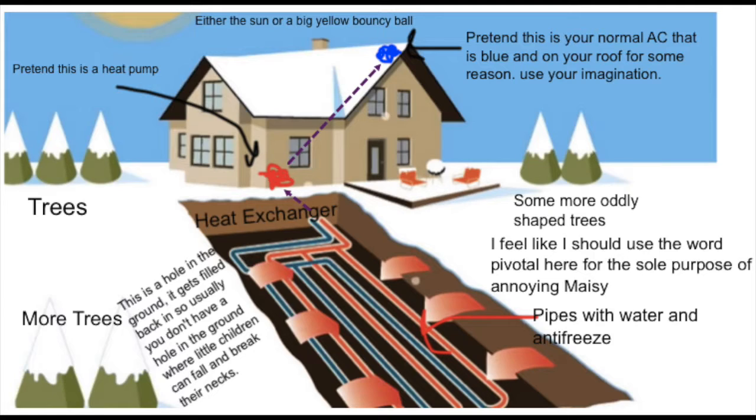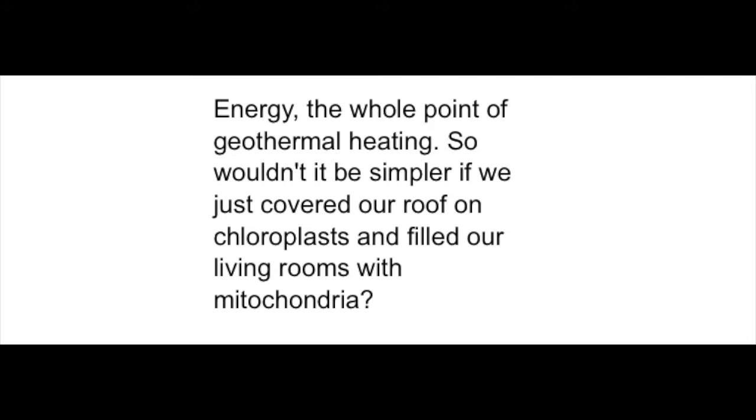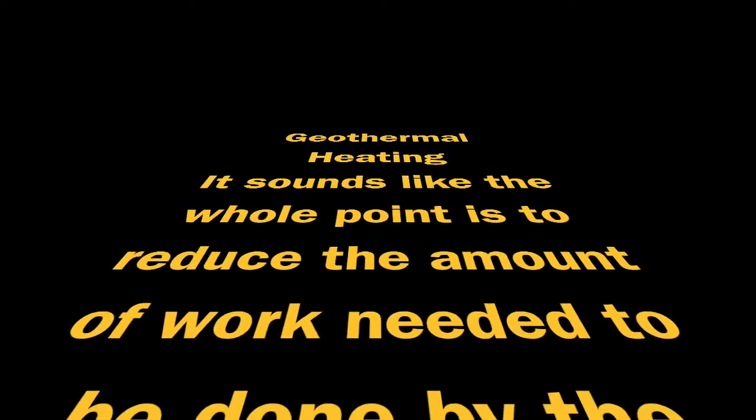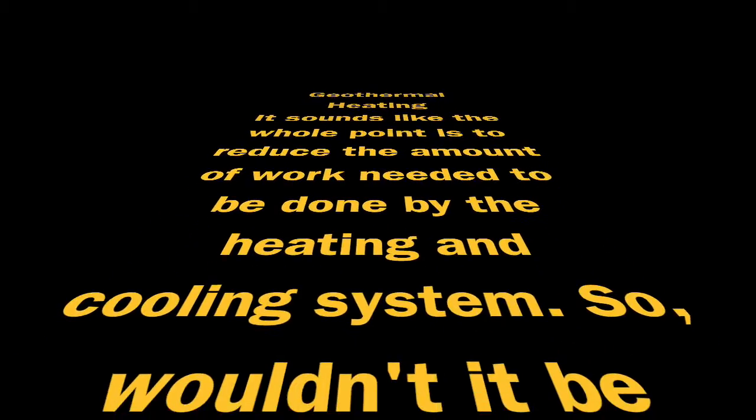In addition to these three systems, geothermal energy can also be utilized in the form of heating. Geothermal heating uses a loop of pipes buried just beneath the ground called a heat exchanger. These pipes are filled with water or a water and antifreeze mixture. During winter, the ground is typically warmer than the air, so the water in the heat exchanger gains energy. Then the warmer water is pumped up to a heat pump, which warms it more, and then the heat is transferred to the normal heating system, where it is heated to a comfortable temperature.